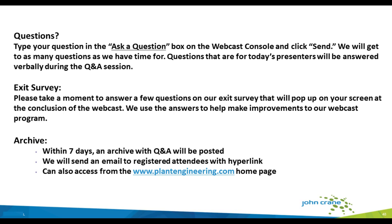Good. We have a little less than 2 minutes remaining, so I'm going to try to ask 2 more questions. Brian, what is the best fluid to use between the faces in a dynamic lift upstream pumping seal? Yeah, so the answer to that question is largely driven by what the owner of that equipment will accept going back into their process, because there is some migration of that fluid.